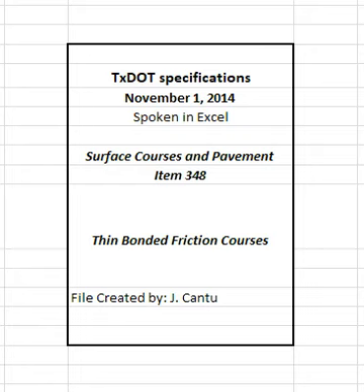4.4.2.1.16 Mixture production. After receiving approval for JMF2, use JMF2 to produce Lot 1. 4.4.2.1.17 Development of JMF3. Evaluate the test results from Lot 1, determine the optimum mixture proportions, and submit as JMF3 for use in Lot 2.